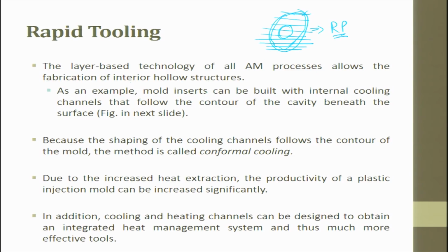As an example, mold inserts can be built with internal cooling channels that follow the contour of a cavity beneath the surface. For example, you have a die, and through the die you want to make a channel. This channel can be made while the part is manufactured rather than at the end, because the shaping of cooling channels follows the contour of the mold. The method is also called conformal cooling.